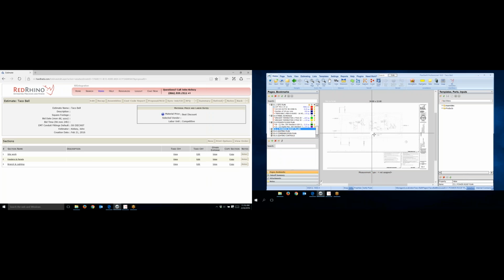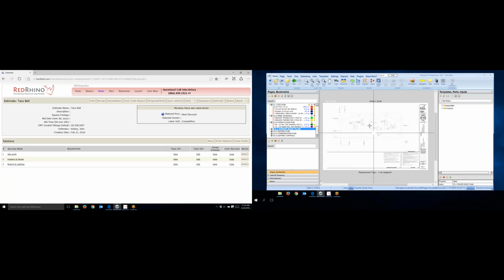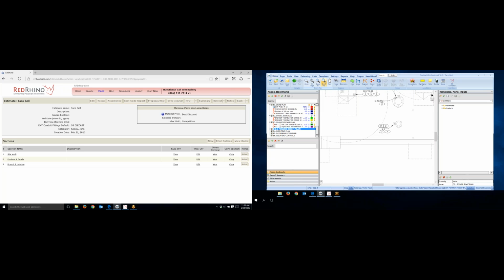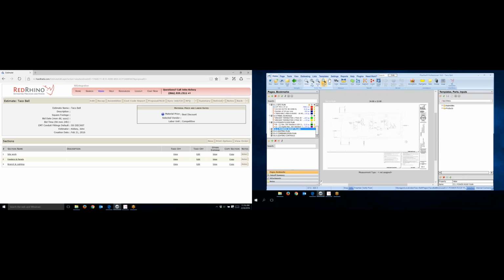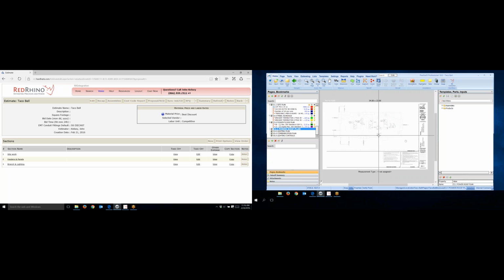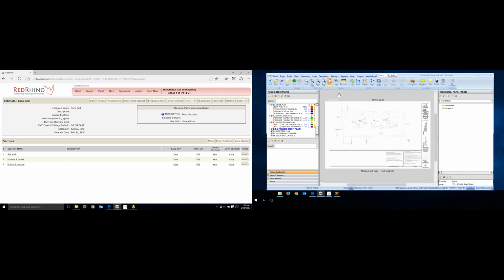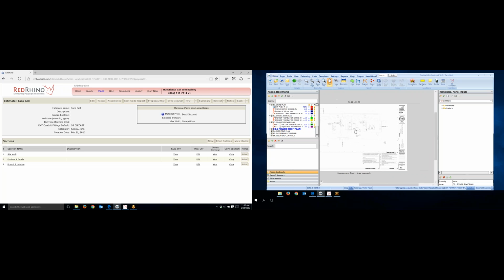It's very simple. Now, here's what I want you to know. What I do is I zoom in on this. I can either click zoom in here and just keep clicking it, and then I can zoom out here, but I have a wheel on top of my mouse, and I just roll it one way and it zooms in, and I roll it the other way and it zooms out. Now to pan, I can click pan here, and what that means is just to move the plans around, okay? So I click on pan, left click, hold it down, and just move it any way I want.